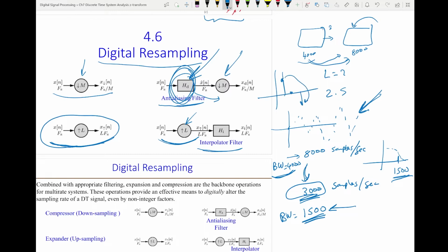Or it could be more sophisticated, like the sinc interpolation. If I want to estimate this value, then I use this sinc interpolation. It's more complex, but gives you a better accuracy. Why? Because with this sinc interpolation, you are not just using the two adjacent samples, you are using even further samples. So you can see the behavior of the signal by using 5, 7, 8 samples to estimate one sample.